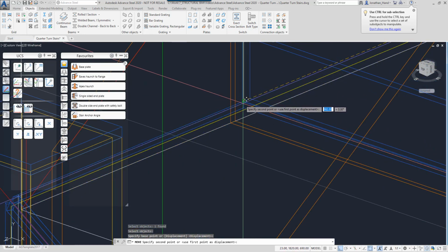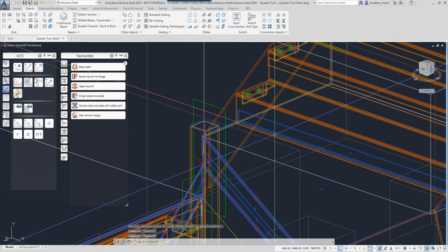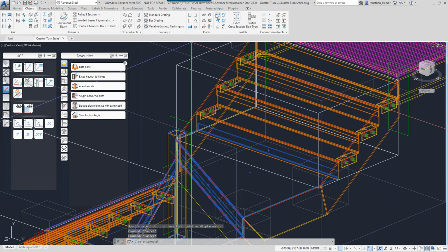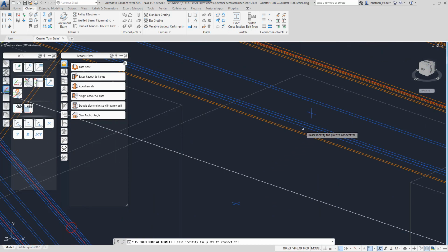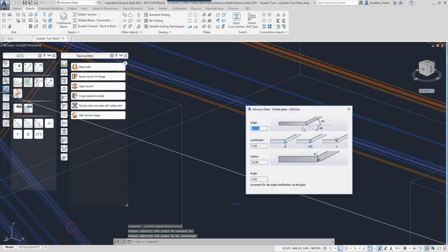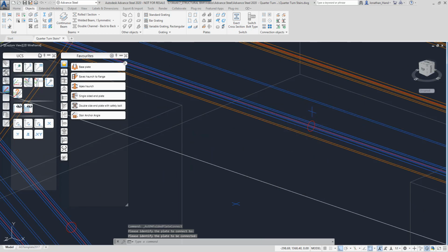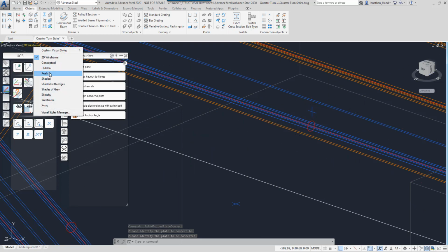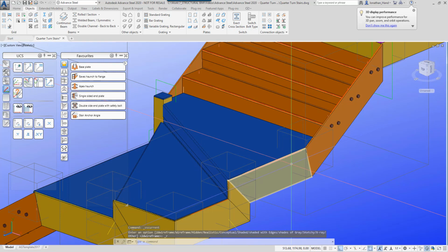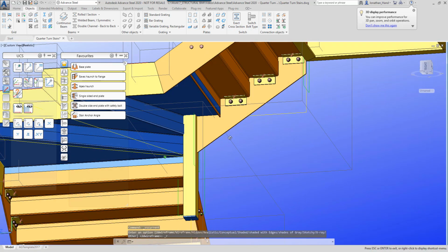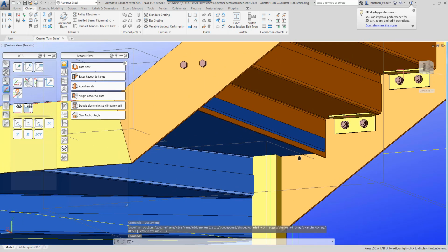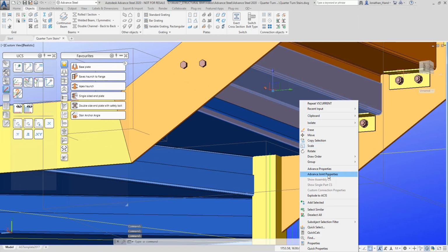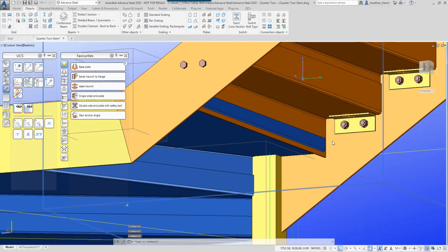So I want it at that position, and then the last thing I think I need to do is just fold one into the other. We have a little look, and that should now fold round the back, and then we just need to adjust that front step height. So I go in to my macro again,